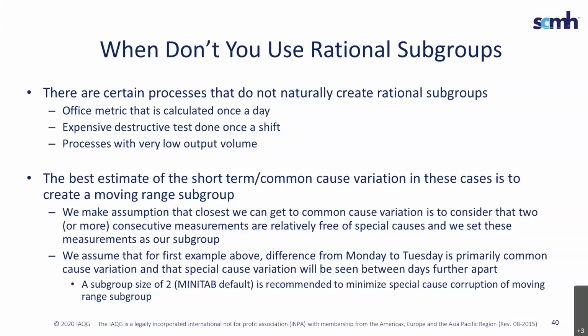In other words, it looks at the individual results, and assumes the successive results are within group variation, as opposed to 5 results in a row being the within variation number. It will calculate that as a rolling number, and I would say use that default of 2 as a good reference for determining the within variation for process capability and stability analysis when you have individuals.